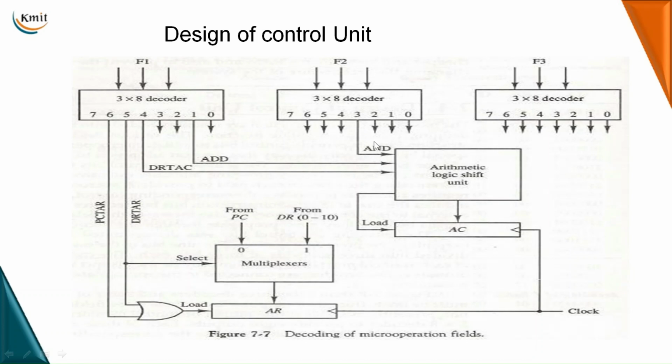It performs a logical AND operation on the contents of the accumulator register and the data register, and the result of the operation is loaded back to the accumulator. From the ALU, the load function is enabled with the accumulator so that the output is written back into the accumulator. So this is how this operation works.